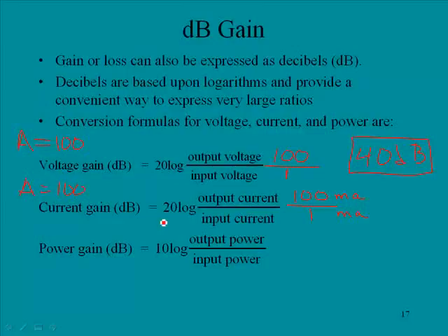Now, if we took 20 log of that, and again it would be just 100, we'd get the same thing. Again, we would say we get 40 dB. Now, the fact is here that this is a much smaller unit. This is in milliamps, but the ratio remains the same, so the output is the same. Again, we're looking at the decibels is unitless. It simply represents the relationship between input and output.